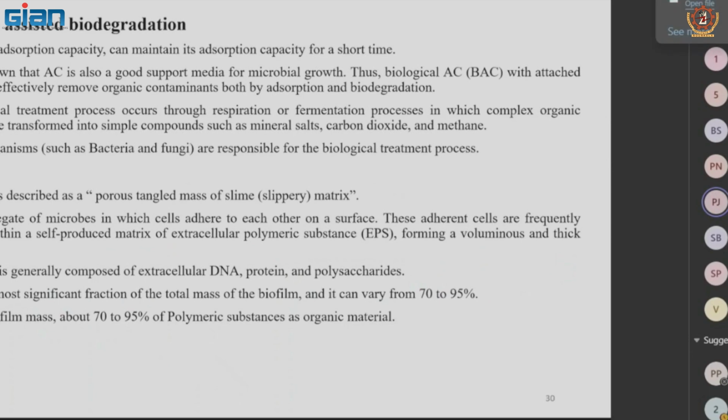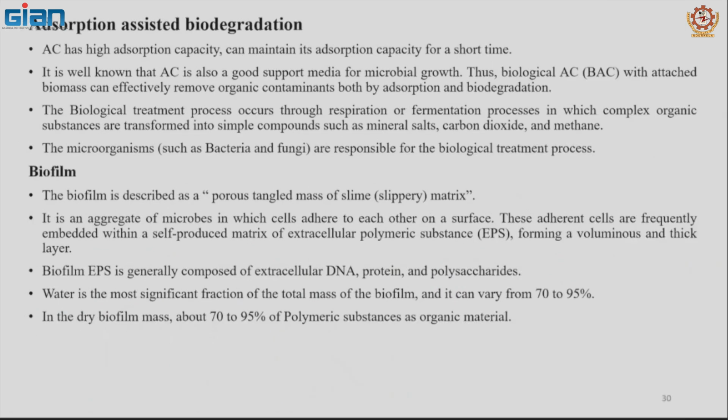Then adsorption assisted biodegradation. Activated carbon has high adsorption capacity, but can maintain its adsorption capacity only for a short time. It is well known that activated carbon is also a good support medium for microbial growth. Thus, biological activated carbon with attached biomass can effectively remove organic contaminants both by adsorption and biodegradation.